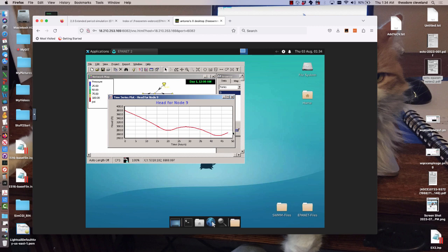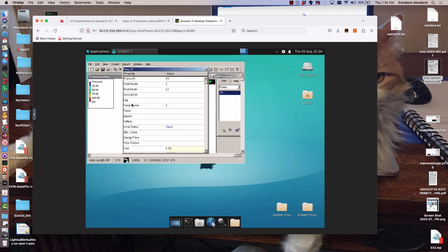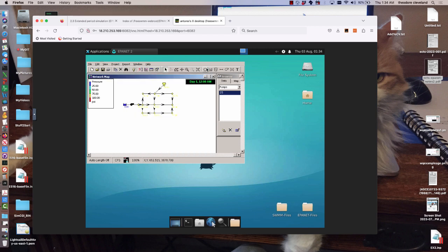Yeah, we're still not quite getting the tank to refill. Maybe what we need is a better pump. Easiest way to do that is to increase the speed to about 1.5. I think that should really crank up the flow rate. Now that's a hydraulic modeling hack. You actually would want to go to a different pump, but let's see what happens if we do that. Yeah, there we go. Good clean run.